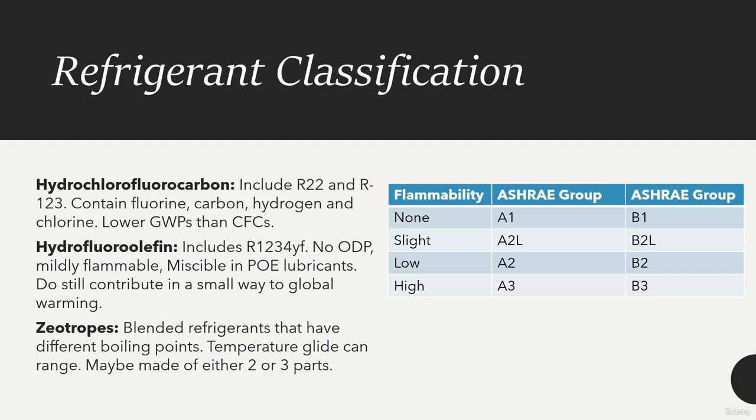Hydrofluoroolefins include R1234YF, which is used a lot in Europe. They have no ozone depletion potential. They are mildly flammable, and they're miscible with polyol ester lubricants, or POE oils. They do still contribute in a small way to global warming.